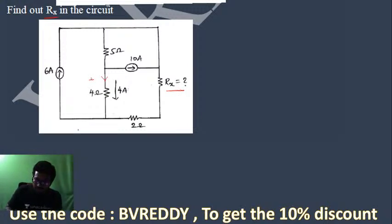Now, this voltage, how much is it? 16 volts. Yes, this voltage is 16 volts. Fine. Now this current is 10. Then how much is this current here? This current is 14 amperes, isn't it? Yes. And this current is 6 amperes, which means this is 8 amperes. That means this current is 2 amperes.